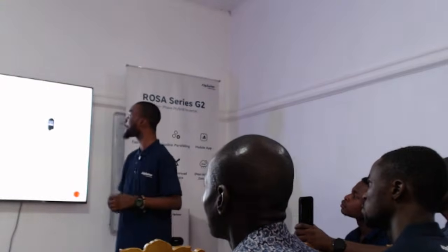For our PV breaker, for our S2 the maximum current coming in is 30 amps and the normal current is 27 amps, so a 35 amps breaker is suitable for your PV. Can we continue? Thank you.